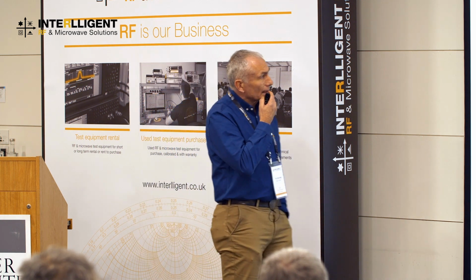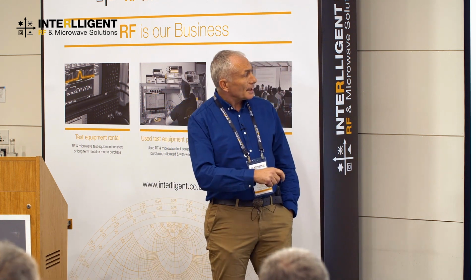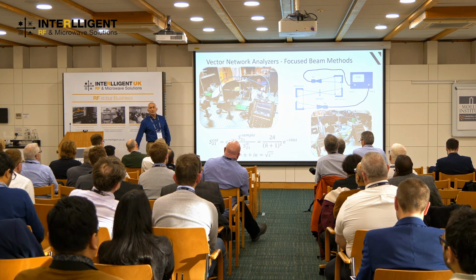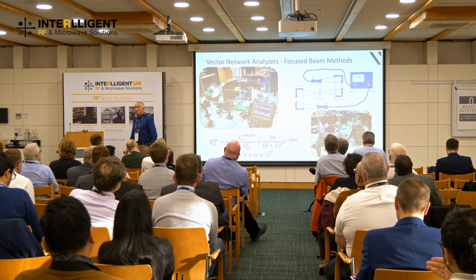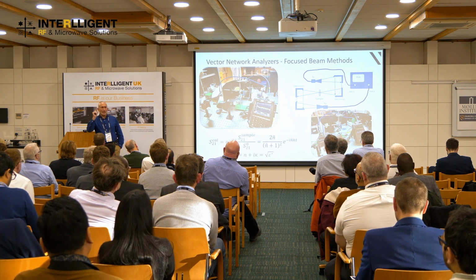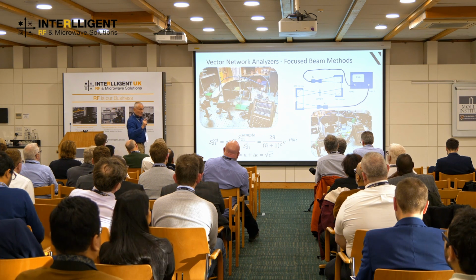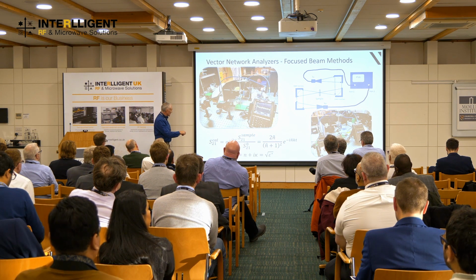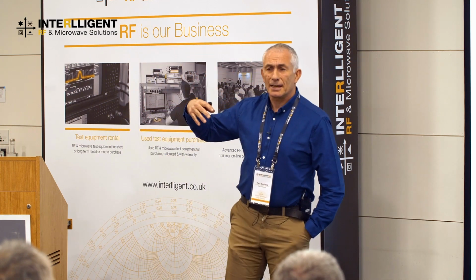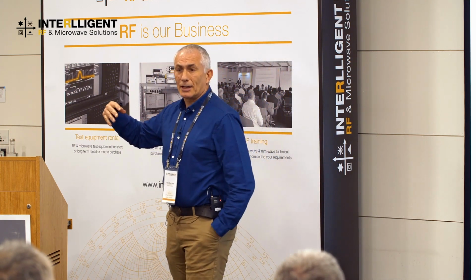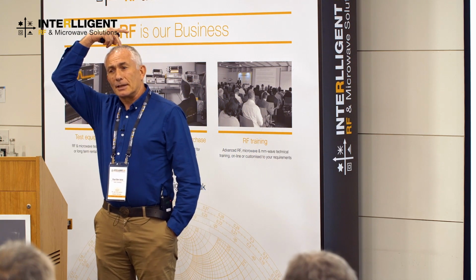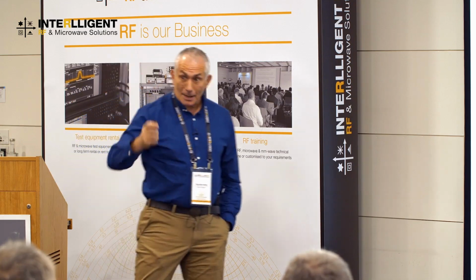Basically, so what are you doing here? Very, very simple. You're simply sending out a wave. We're collimating it. We are focusing it. Now, of course, that focusing is only going to be to a spot about one or two wavelengths in diameter, so you are limited. This technique we did from about 25 gigahertz and above. If I was to do that technique in the megahertz region, the lens required is basically my height. So it's a little impractical and a little difficult to do. But it can be done.